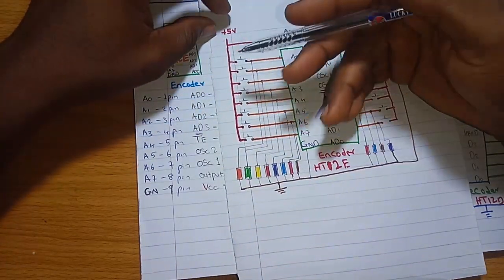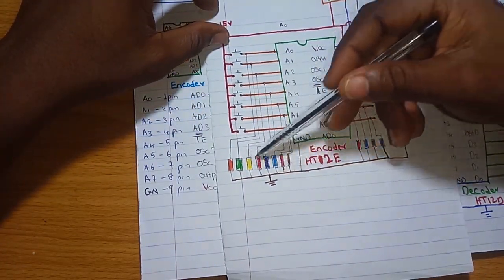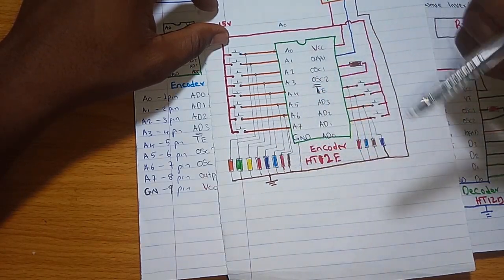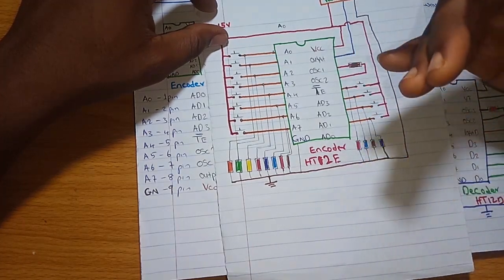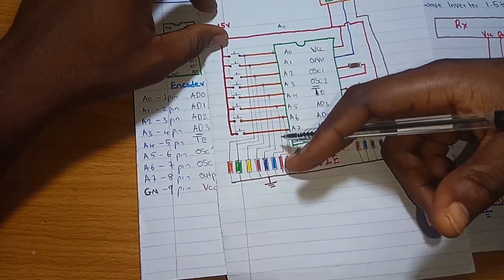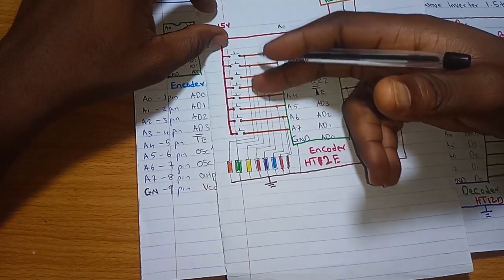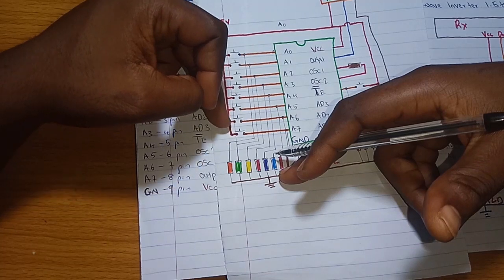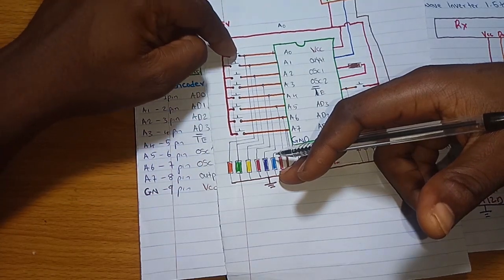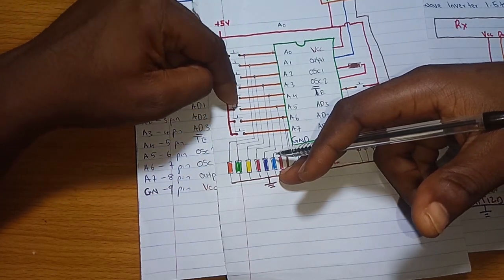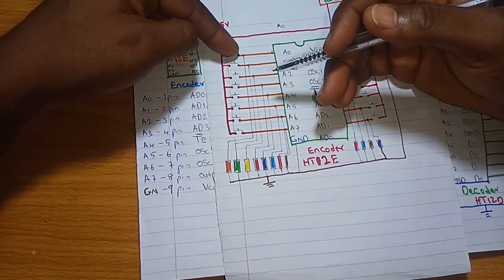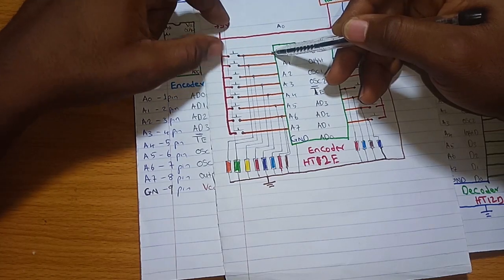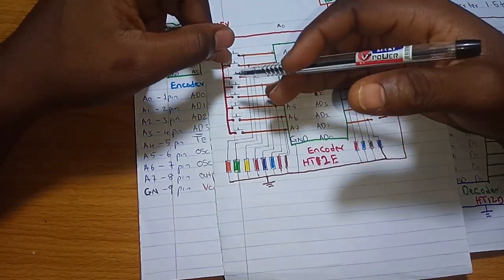So I use this resistor. Don't mind the color, I just use the color to beautify the resistor. You can use a 1 kilo ohm resistor in order to put all these pins to ground. So what I did is that I put all these address pins to ground and used a pull-up signal by connecting each of them to a push button, so that if I press this button, this pin will be pulled high. If I release the button, the pin will be pulled low. So that is what I did here.